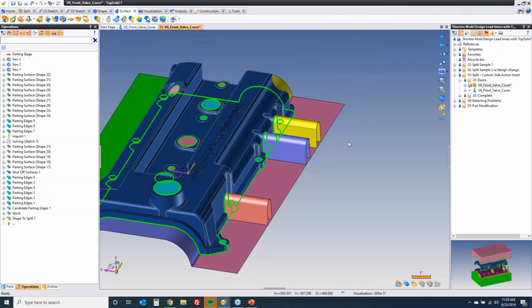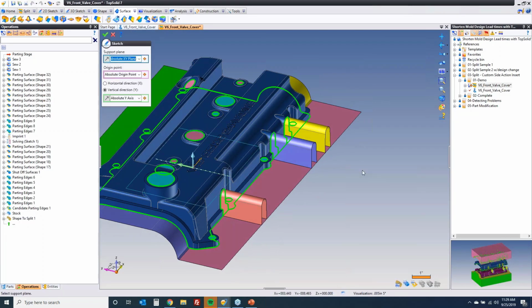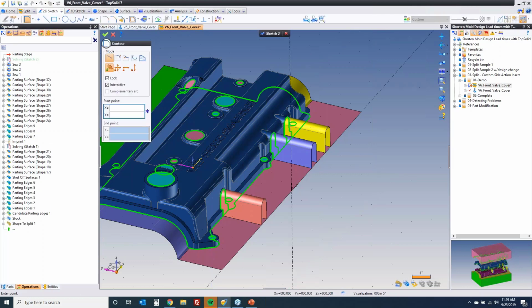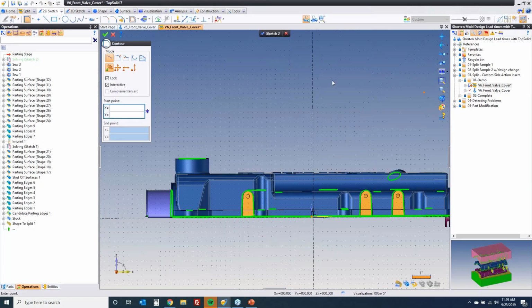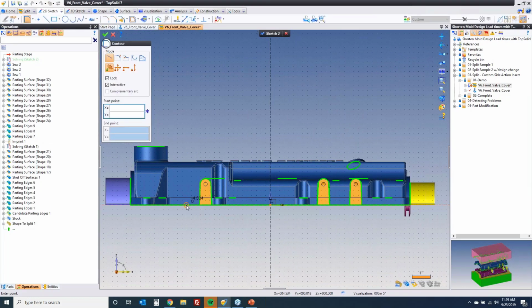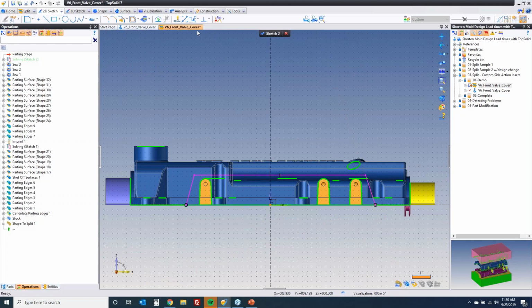Good. Now, next, I'm going to build a sketch on one of those stock planes, this one again is going to be the Y-. Perfect. And now let's maybe look straight at it. I'm going to come over here, come up at some angle, come over, come down at some angle, and we'll come back and close this. Now, I do need to add some dimensions because I want this to be to some specific size.